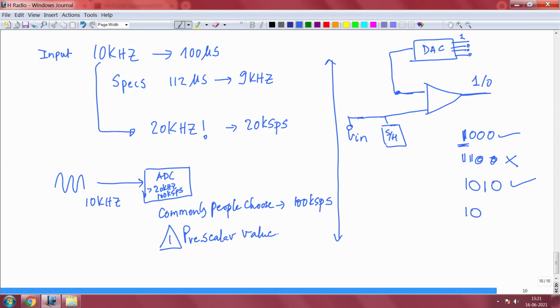This failed, I will leave that. This passed earlier, now I will try this. If this also passes, then this is the output, finished. So each time you do an approximation, you do a comparison, and that comparison is what is fed out. So you do one bit at a time, one MSB position at a time, and keep rotating it. So let us go back, and I hope you got this picture. If you indeed got that picture, let us go back and look at this one.